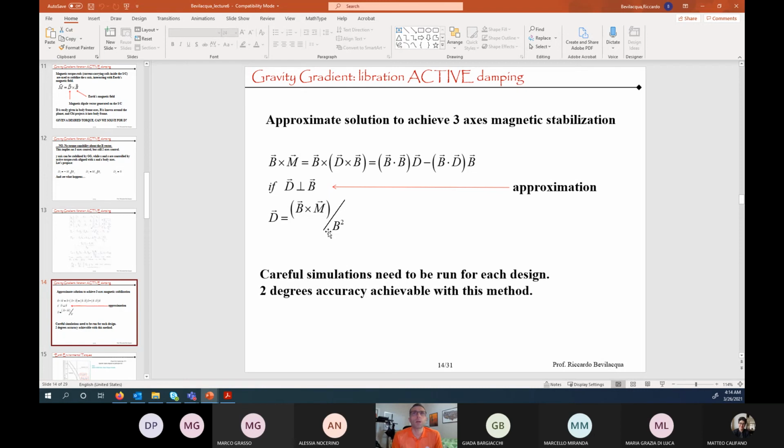Now, I said before when we started the class that for the most part, this type of interaction with the environment is used for detumbling. So the most common use really is either complementing for gravity gradient, as we've seen, or just removing omega, removing any angular velocity after deployment, or bringing it down to very small values. So the reality is that nowadays we don't really control orientation with this kind of torque. We mostly just detumble the spacecraft. Okay. All right.